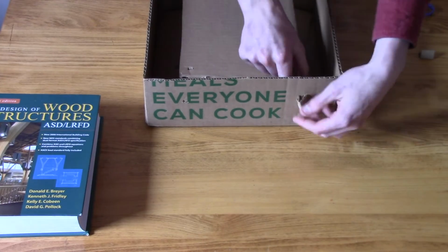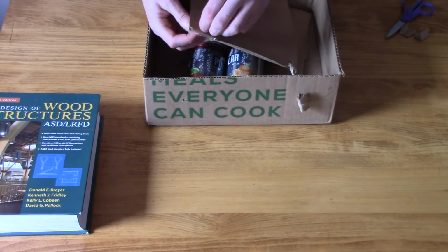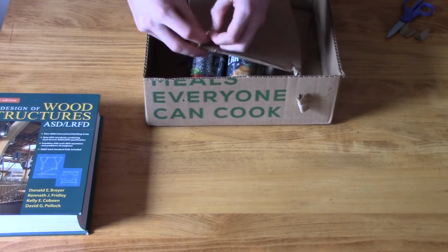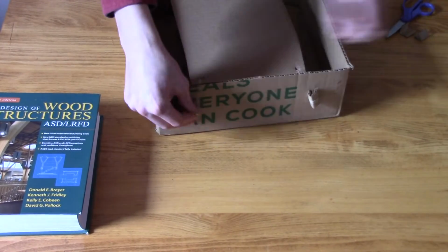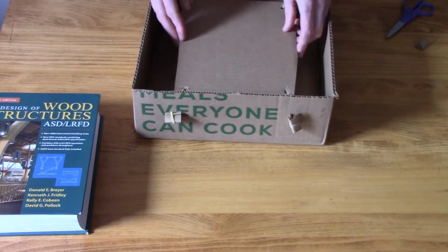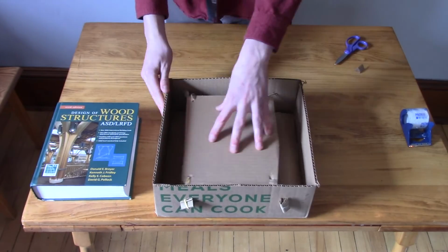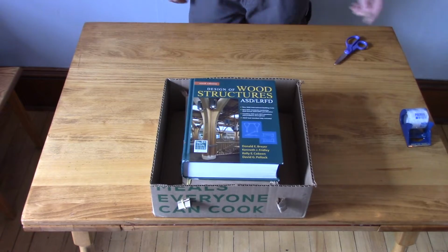This is significant to engineers because if the period of the ground's movement is similar to a structure's fundamental period, an effect called resonance will take place. Resonance leads to extreme movement of the structure, which generally leads to the structure failing. In this activity, we will observe how structures of varying heights may react to the earthquake we model.